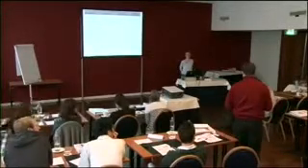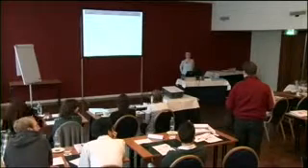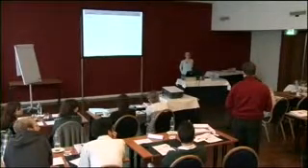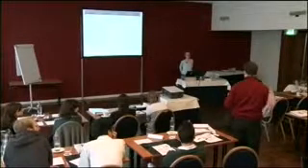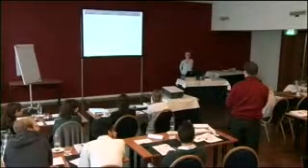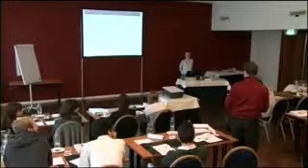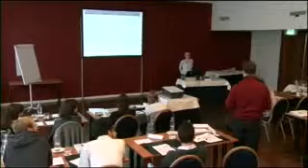You have just mentioned the time scale on which this adsorption experiment will go. I learned in a course in the past that the time scale of the adsorption experiment is always a bit critical, because one never knows when it's actually finished. So how is that dealt with? Well, normally you would measure the weight change as a function of time, and at a certain time you will see that there are only small changes.